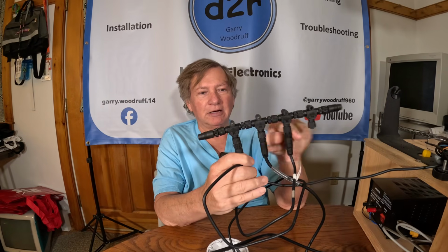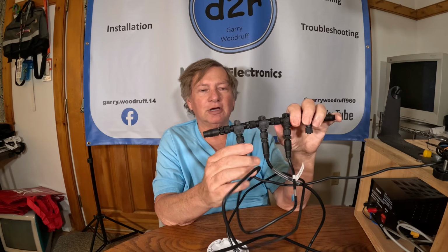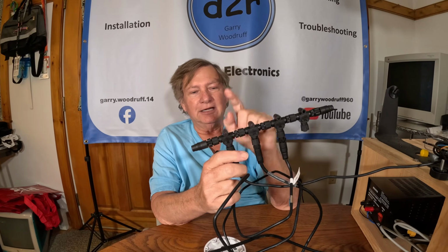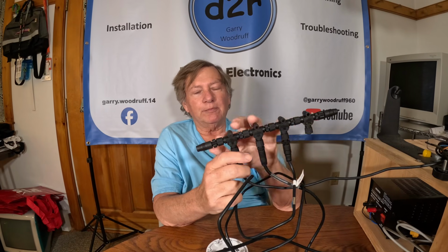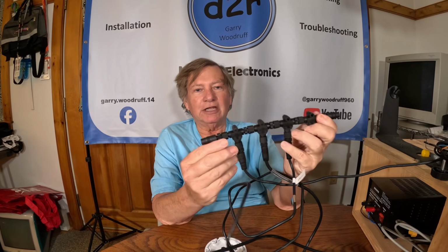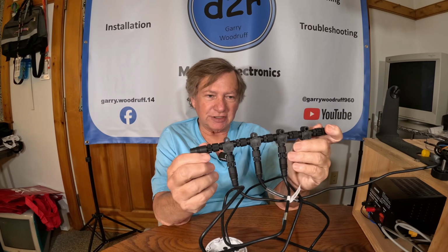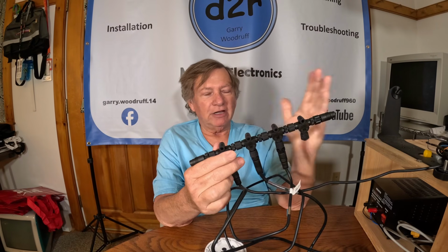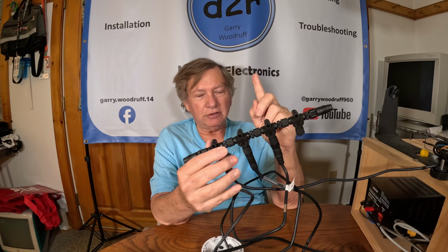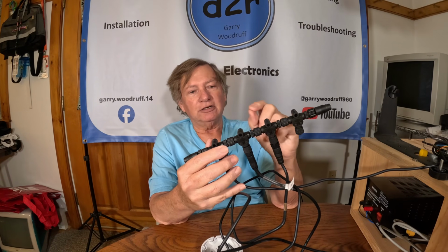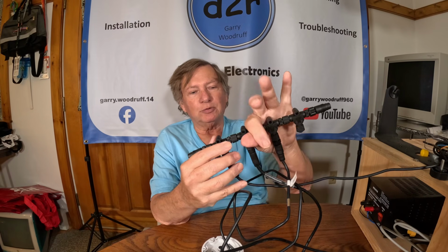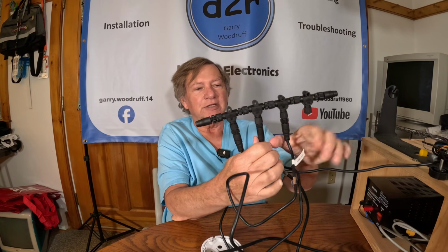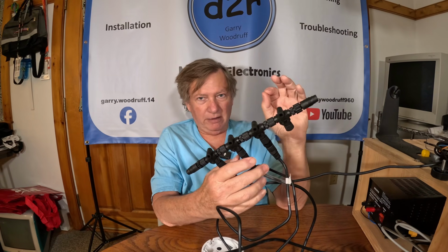Everything comes off the bottom from a T. The T is a form of your backbone. The end of the network has terminating resistors, and you've got to have one power node. There are power isolator nodes you can get, so you can put one in between here and isolate this set of power from this set of power if you need to.